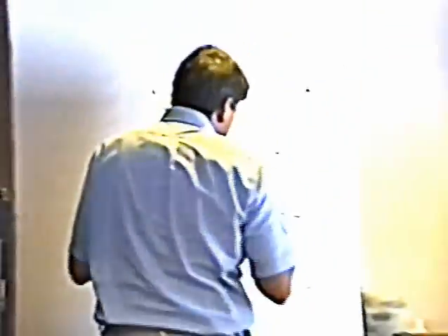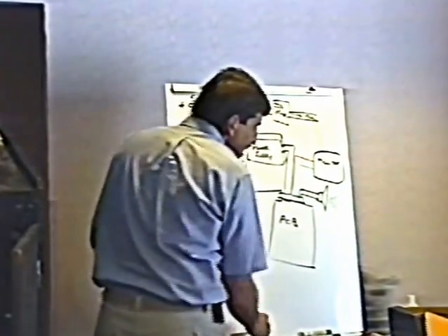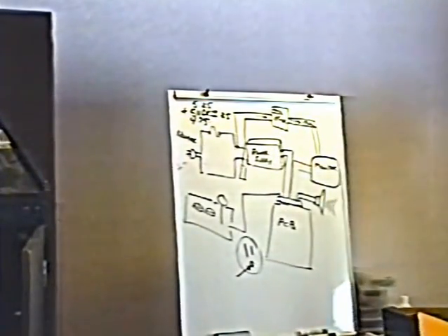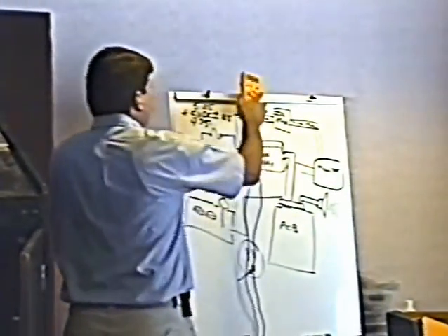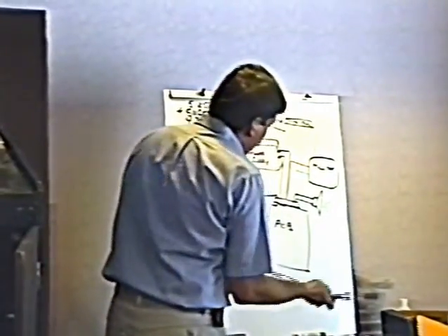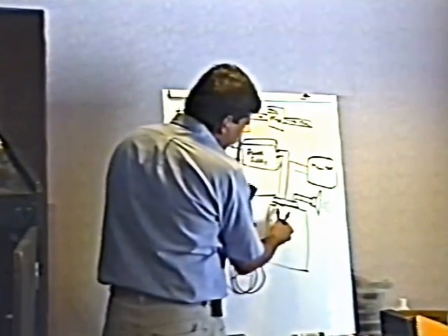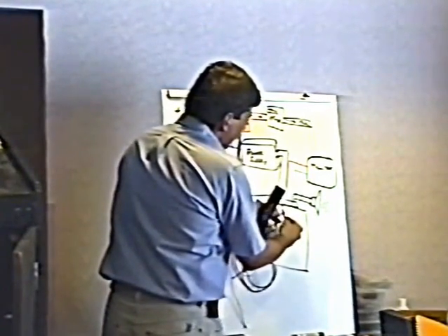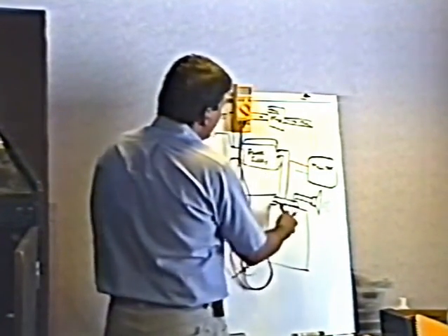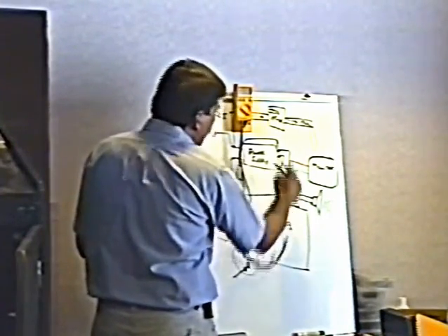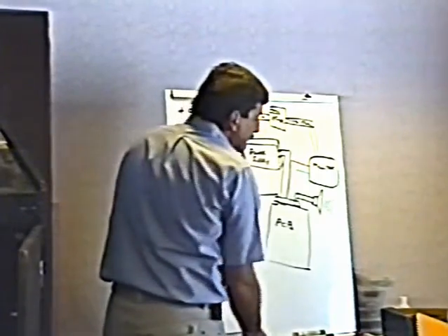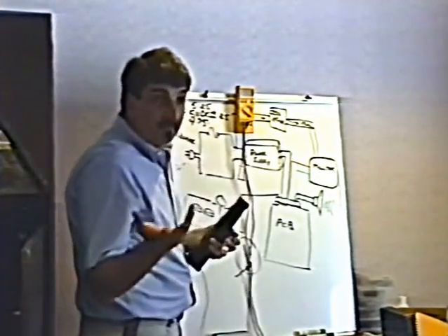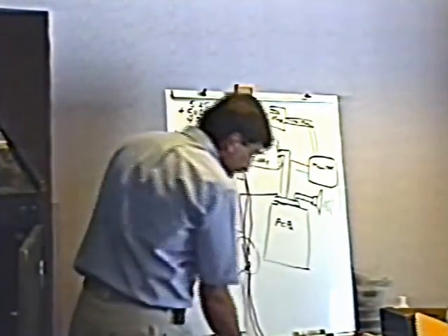When I want to measure the 5 volt power supply, I measure it here at this connector. With the power turned on and the meter set on DC volts, I put one meter lead on ground and the other meter lead on plus 5, and with my meter connected to the board, adjust the voltage on the power supply. Now that kind of takes 3 hands to do it. There's a couple of ways around this.